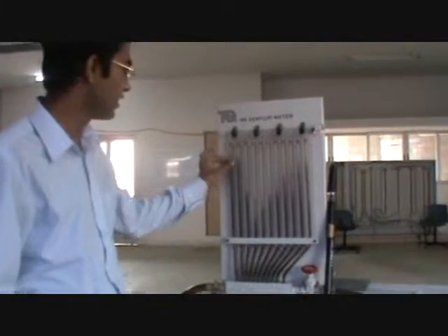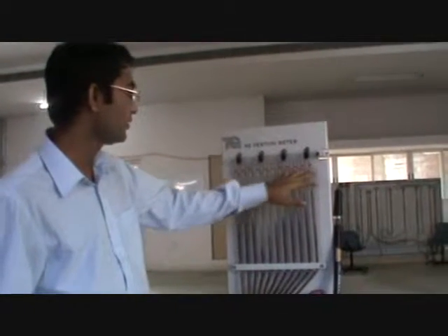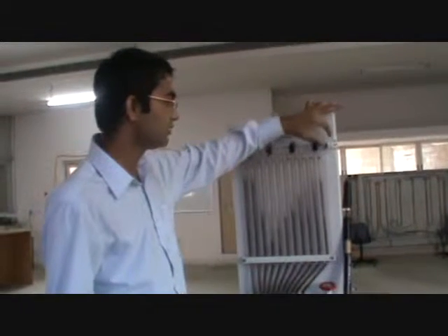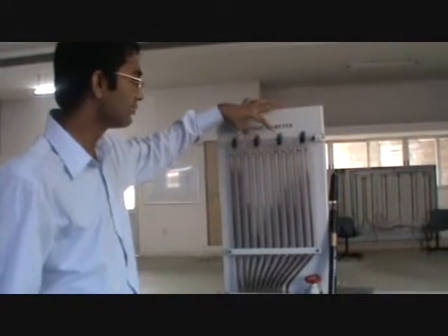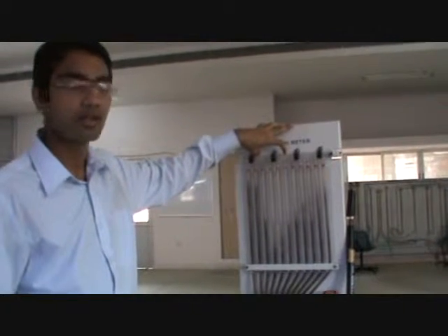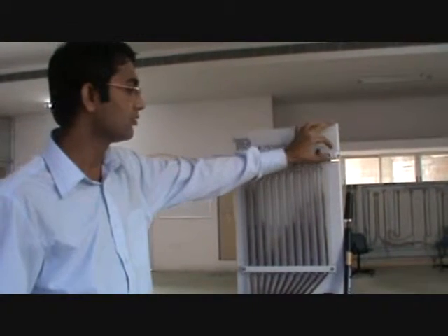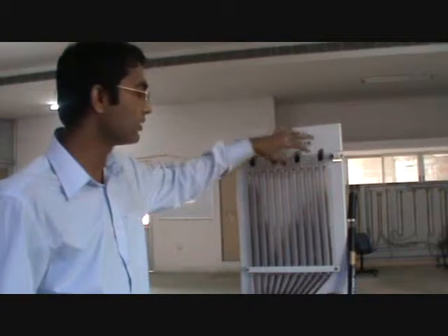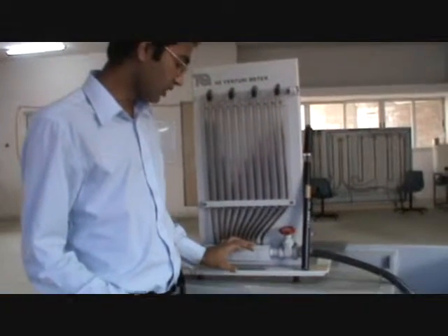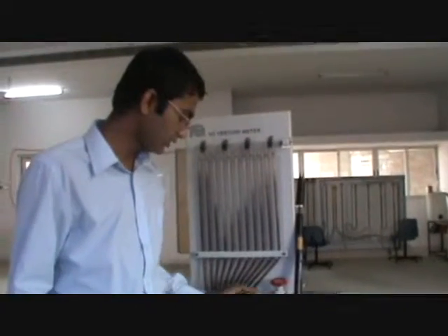So this is the manometer, and all manometers are connected to the common manifold here. This is the pin of the manifold. It is meant for removing any air bubbles trapped inside the water, so we can just open this pin so that the air can be removed from here. Then we have to control the flow of water through venturimeter.